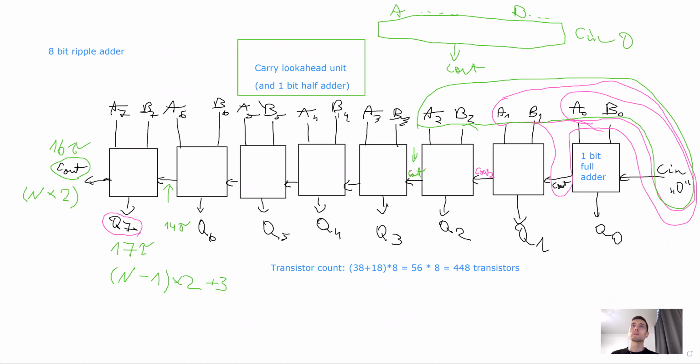And you can also create sub-circuits. So basically you create, for example, a 1-bit full adder from logic gates, and then you tell the program to use it as a building block. And instead of building everything just from NAND, NOT, and NOR, you can drag and drop your custom built building blocks into higher level circuits, and you can easily create such an 8-bit adder and test it out. So do lab 1, part 1, part 2, and part 3 for the next lesson. And then in the next lesson, we will check out what more we can do with a simple 8-bit adder. You'll be surprised, actually. So, okay, that's all for today.